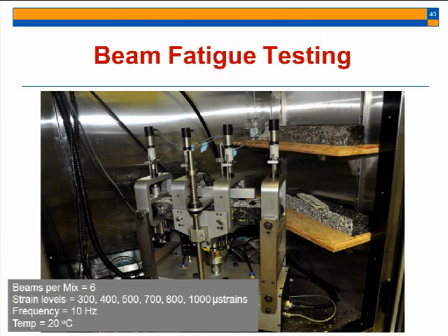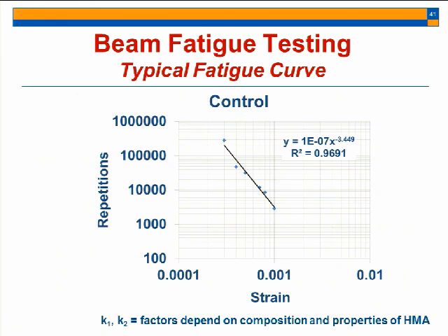Then we did the beam fatigue test on it as well to measure the flexural resistance of these mixtures. 6 beams were tested, and the strain levels that were used were from 300, 400, all the way up to 1,000 microstrains at a frequency of 10 hertz and 20 degrees centigrade. This is the typical fatigue curve that we obtained from these 6 tests that we conduct on these samples. And there was a simple relationship shown here between the number of repetitions and strain.